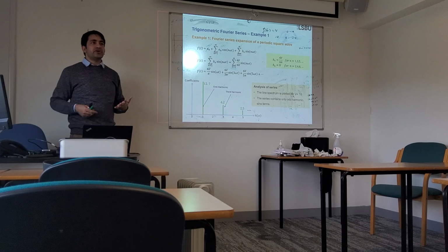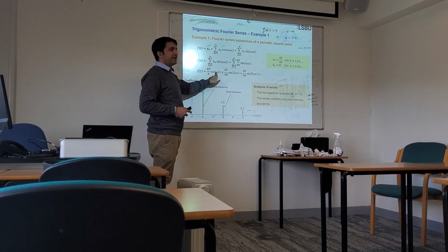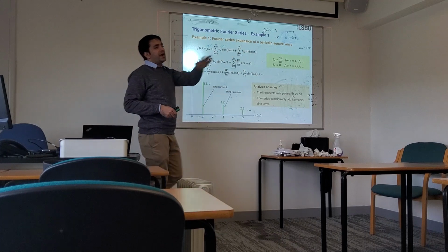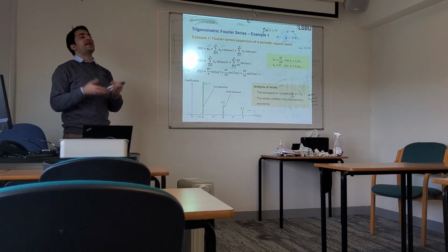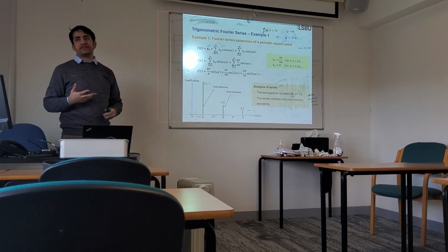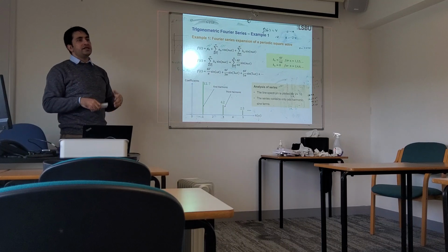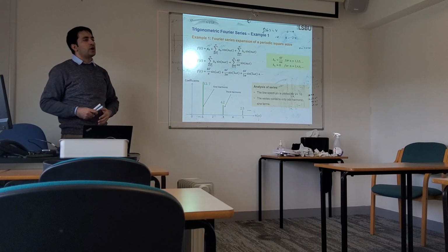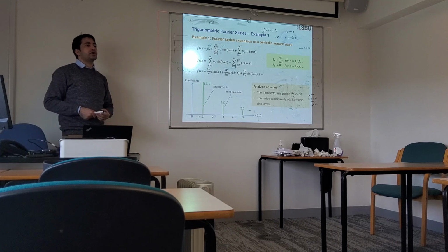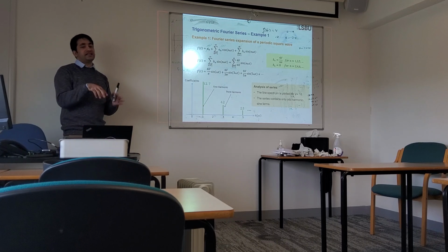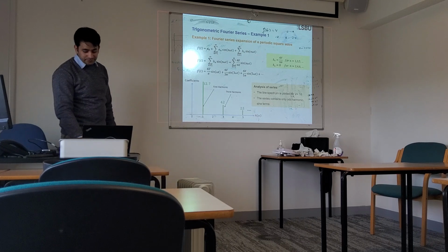But if it is not pure AC, you will see an omega term and so many other things. All those other things are called harmonics, unwanted signals. So for power systems, Fourier series is very useful, so that you analyze a signal for power quality, whether this signal is good or not, what frequency it has, and whether this signal is good for certain equipment or not.